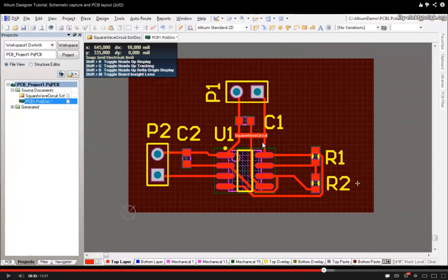For some of the components that we have in our circuits, we couldn't find the floor plan, the layout, in this software. So we had to create our own, which is not that hard because a PCB is just a layout. If you know the size of a component and the pin distance, it's really easy to create your own. You just have to add the pad onto the PCB, and then make sure that the distance is exactly what it is on your component,